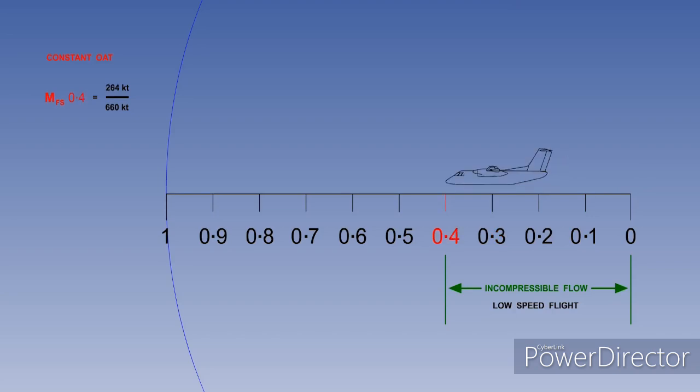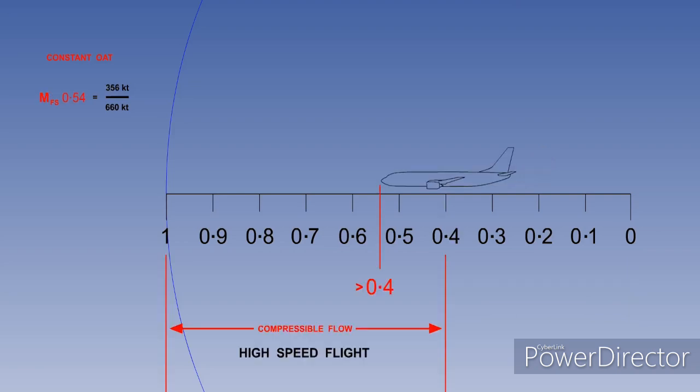And a turboprop commuter aircraft at Mach 0.4. All these examples operate at speeds less than Mach 0.4, when their proximity to the leading pressure wave has no significance. It is only aircraft that operate above Mach 0.4 that need to know their proximity to the leading pressure wave, and consequently will be fitted with a Mach meter to tell the flight crew the aircraft Mach number.